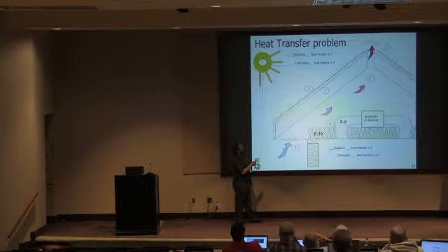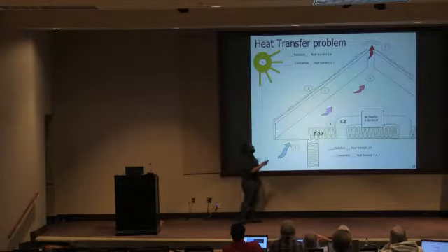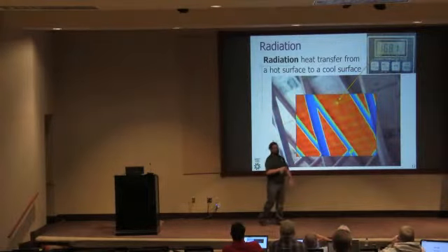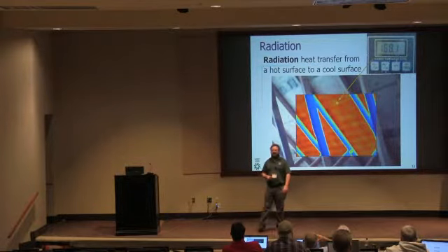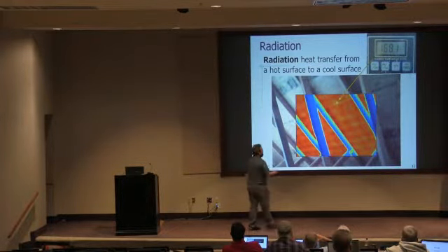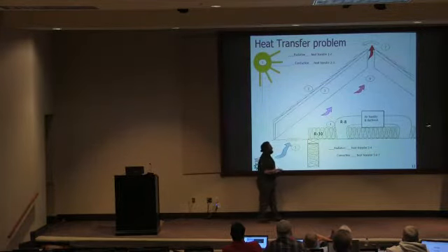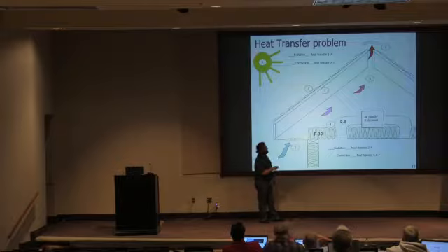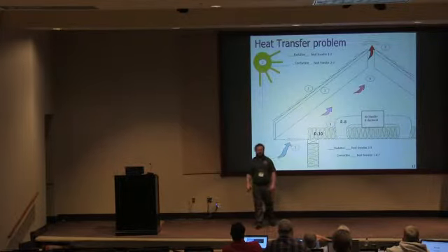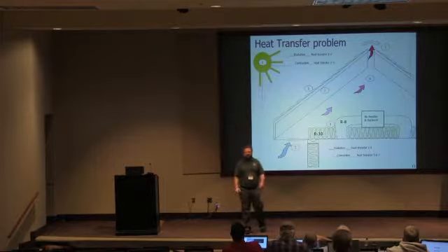Then the heat builds up, and it starts to conduct from hot to cold. These surfaces are cooler, so it conducts through the roof assembly. Then the backside of this roof deck does what? Like I just showed you, it gets really, really hot, 160, 170 degrees surface temperature. Heat starts to radiate off the backside of this roof deck. It sees these other surfaces, your insulation, your air handler, your ductwork, your framing. It starts to warm up these surfaces. And then eventually the air temperature builds up in the attic. It gets to be 110, 120 degrees up there.